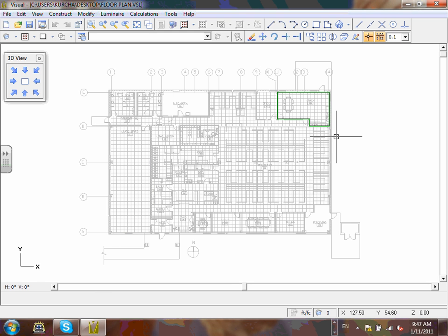From now on, guys, if you're ahead, all you have to do is just keep building rooms and hallways. To do a calculation, you have to build rooms, and you can't do a calculation without building solids. So for every room, you're going to trace a solid, give it a name, make sure the height of the ceiling is good, and click OK, close it, done. Check, check, check. That's step number 1, building the solids for the whole room.